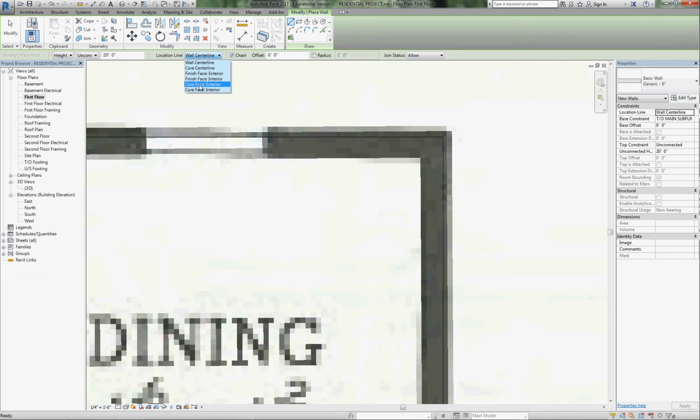So just from a starting point, you can see later on we're going to trace the interior walls. You don't have to be perfect on your initial wall positions, because we can change them just by selecting the dimensions. So for example, let's say this wall, we didn't eyeball it perfectly and it was out there. Well, I can click on it and get a dimension that I'm in charge of. Now this dimension defaults to the center of the wall, but I can drag that little blue dot to the outside of the wall and do the same down here to the outside of the wall.